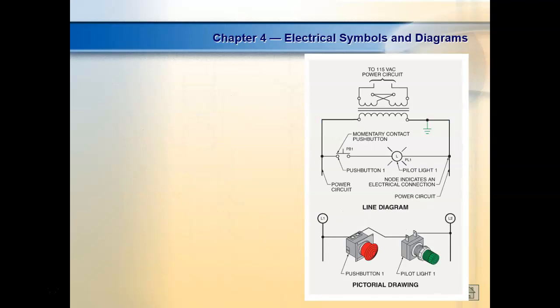So this is a dual voltage transformer. We looked at that a little bit, right? Everybody understand? Wired for high voltage because the primary coils are hooked in series. This would be considered L1. This would be considered L2. And I need to do this, guys, because I'm recording this.